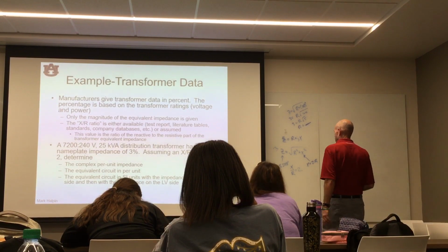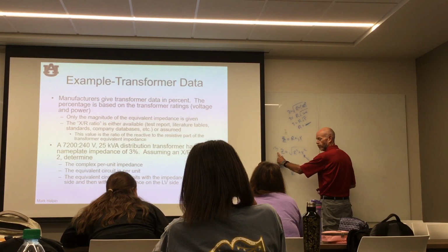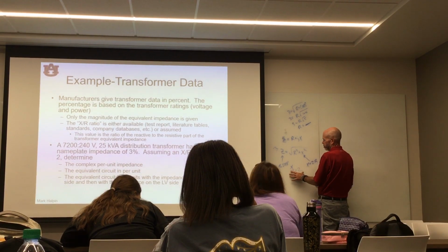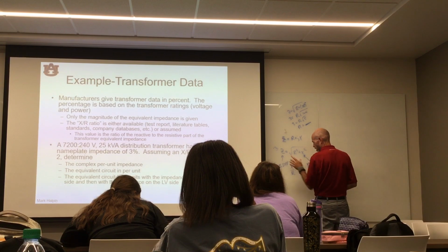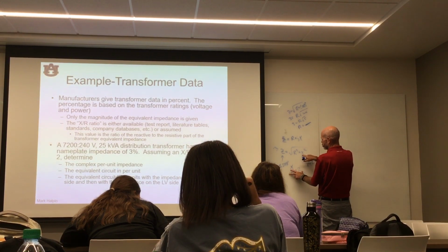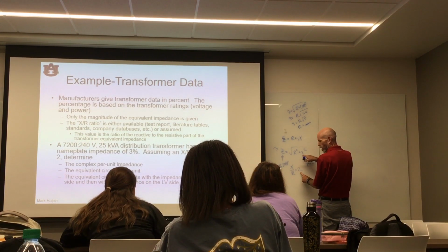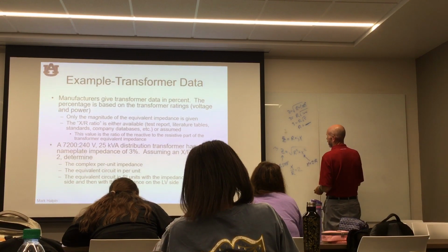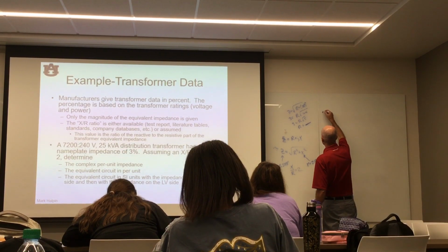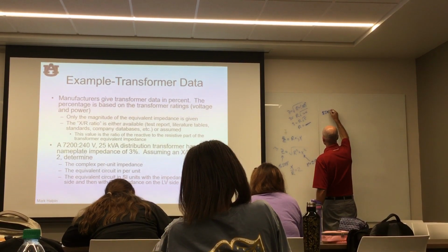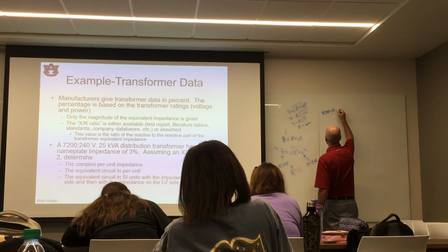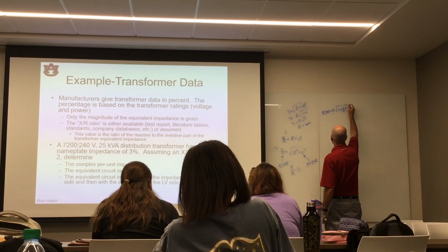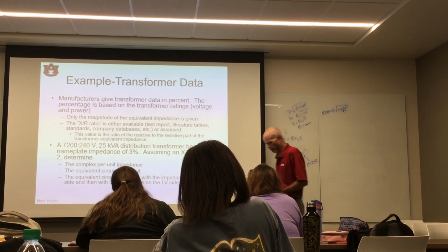I always do it the same way. I get this off the nameplate, and I get that somewhere, either from experience or wherever. I get that off the nameplate, I have this, and I just plug it in right there. I'm going to put that 2 right there. So in my mind, I'm always saying that the percent impedance is equal to R times the square root of 1 plus whatever that X to R ratio is squared. That's what's in my brain every time.